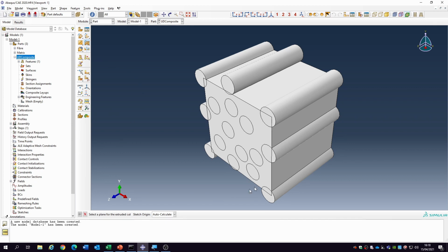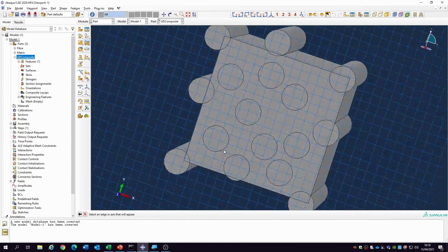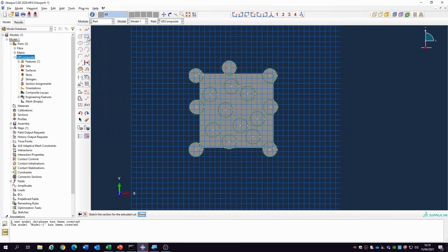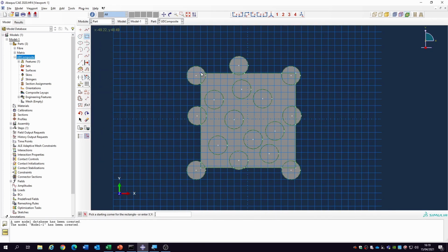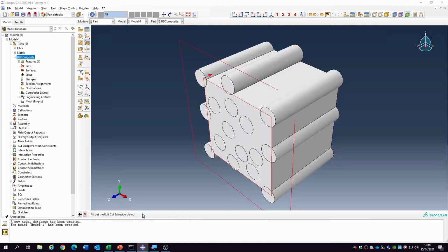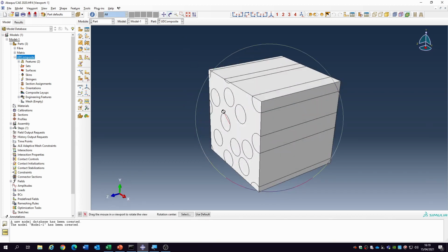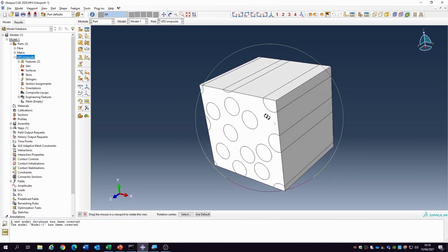Select the plane to extrude cut. So we select, okay, I want to extrude, and then select the edge. I want this edge. I'm going to use a way of extrude cutting this. I click on the rectangle button, start on one corner of the matrix to the other corner. So we've got that, and build a bigger one around it. This would give you a way of cutting, trimming off what's on the boundary. Right click, cancel, and click done, and then click through all. So it slices through everything, giving you a clear RVE that looks the right kind of RVE that we're interested in.